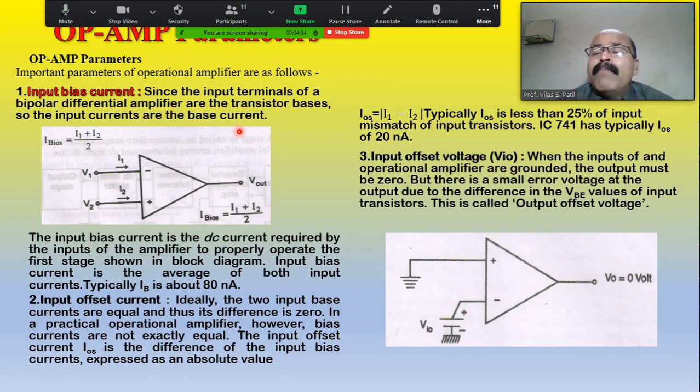That amplification is known as beta equal to IC divided by IB, and it is about 50 to 500 in the case of a common emitter mode transistor amplifier, more commonly known as current gain.